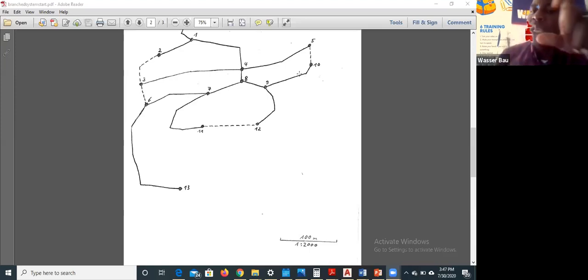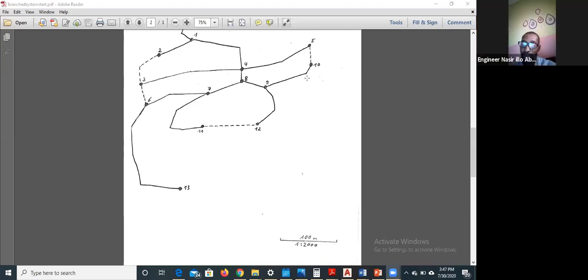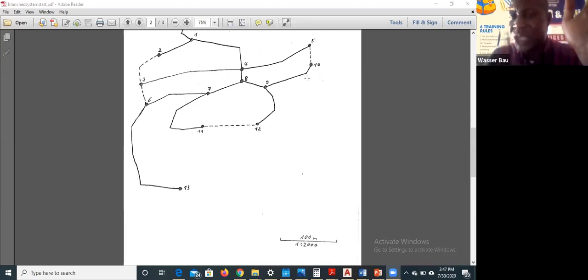But the problem is that loop systems are very difficult to design, but there's a way to design them. The way is to make use of dummies, because that's where you start applying things like the Hardy-Cross method. You have to do interpolation and iteration, because what you're trying to find is the best value. It's like critical paths in project management, where you look at the easiest flow path. But save yourself that energy for now.